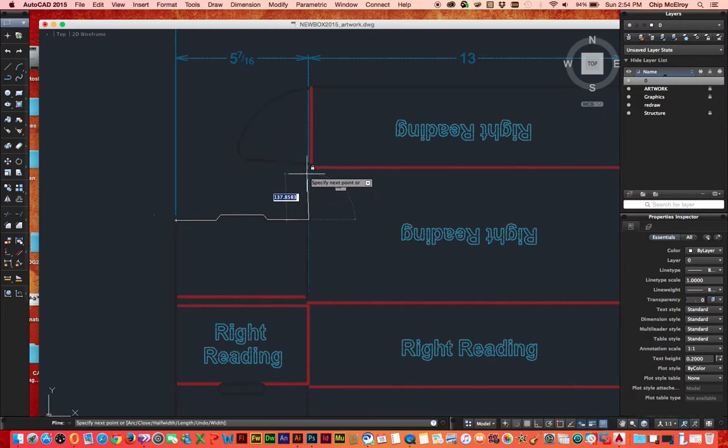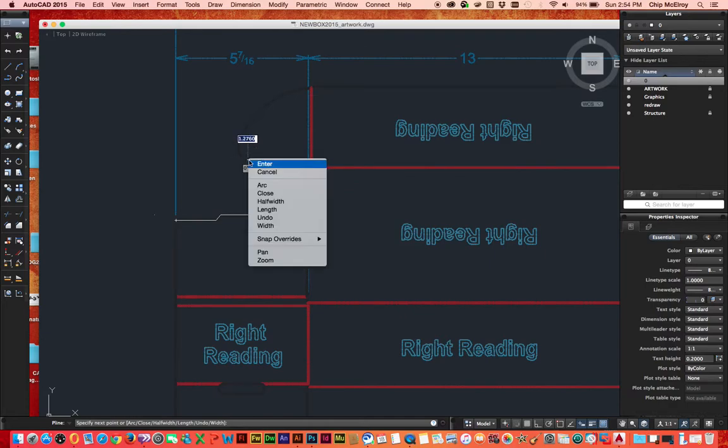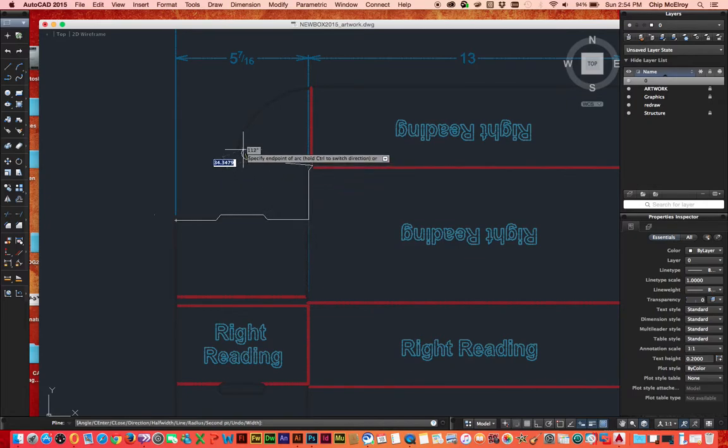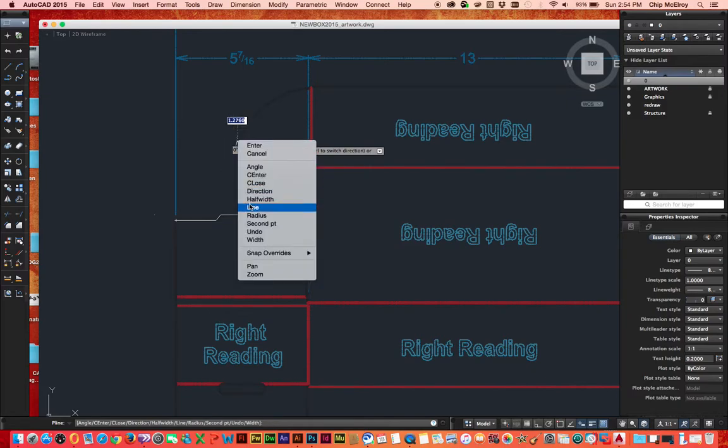And I'm going to go up here. I'm going to go ahead and add that point. I'm going to go in the corner here. Now I'm going to take my angle here. And right when I get to the tip, I'm going to go ahead and right-click on this node. And you're going to notice that by right-clicking, it gives me access to draw the arch, and I'm actually going to create an ever so slight arch here. Go ahead and click there, and then I'm going to right click again, and I'm going to change back to my line tool.